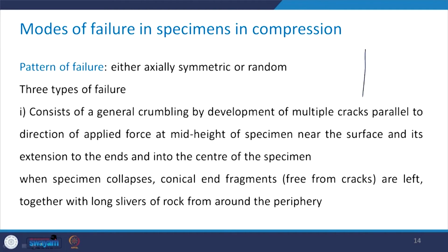Take a look here, this is the specimen, and this is the direction of the loading, and this is the center of the specimen, let us say. Multiple cracks are going to be there because of this applied force, and slowly as the load is increased, these cracks get oriented in the direction parallel to the direction of loading.